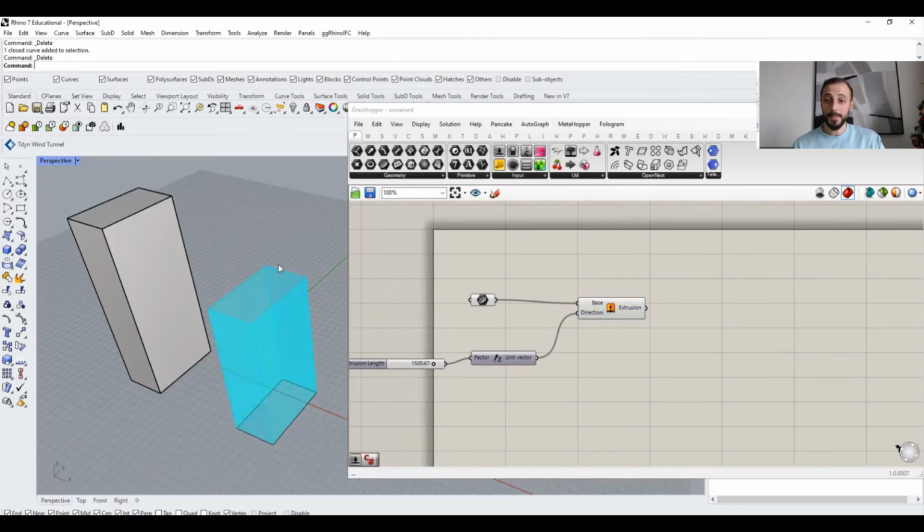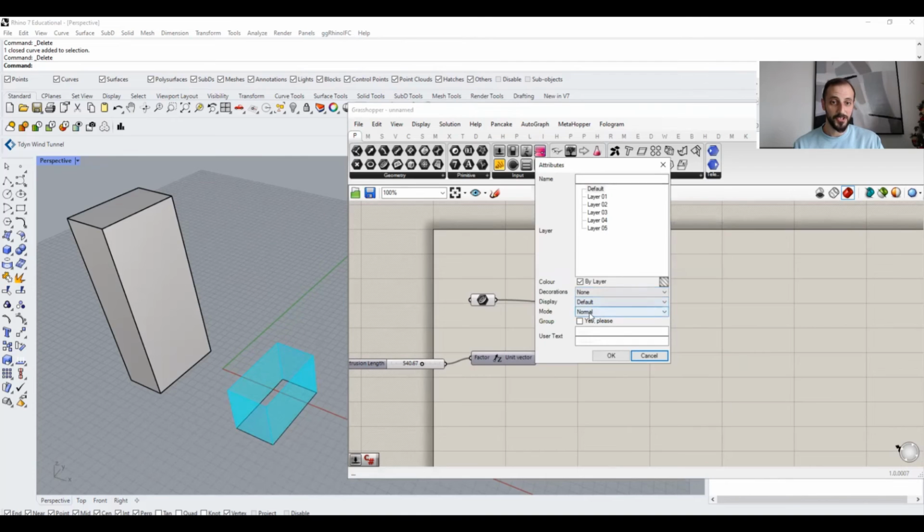But how will I be creating this in Rhino, right? So what I need to do is right click on this and say bake. You see an egg here. And when you say bake, it will ask you which layer you want to bake the geometry on. So if I say layer 1, you can put a lot of different things related to the bake geometry options, such as in which color it's going to be used. You can select the colors here,